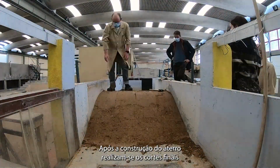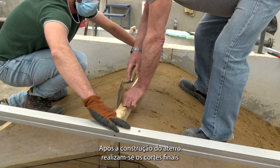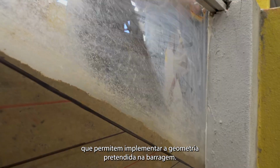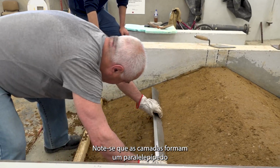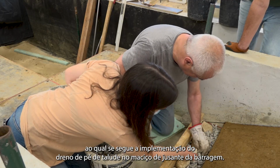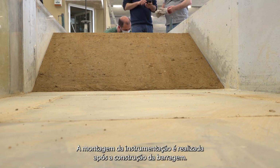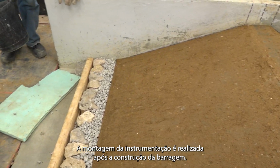After all lifts have been raised, the last step corresponds to the final cuts that allow achieving the desired shape of the dam. Note that the lifts form a parallelepiped, followed by the implementation of the toe drain in the dam downstream slope. Instrumentation is set up after finishing the construction of the dam.